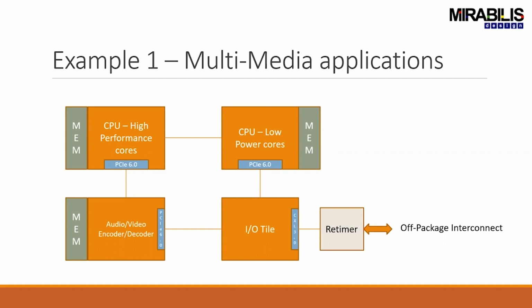So again, the issues that come up are all the details regarding the interfaces here, to really be able to understand what the memory accesses between dies are. Are you going to be making IO requests? What's the size of these IO requests? How many concurrent requests are being made to the IO from multiple devices or multiple dies? All of those need to be considered.